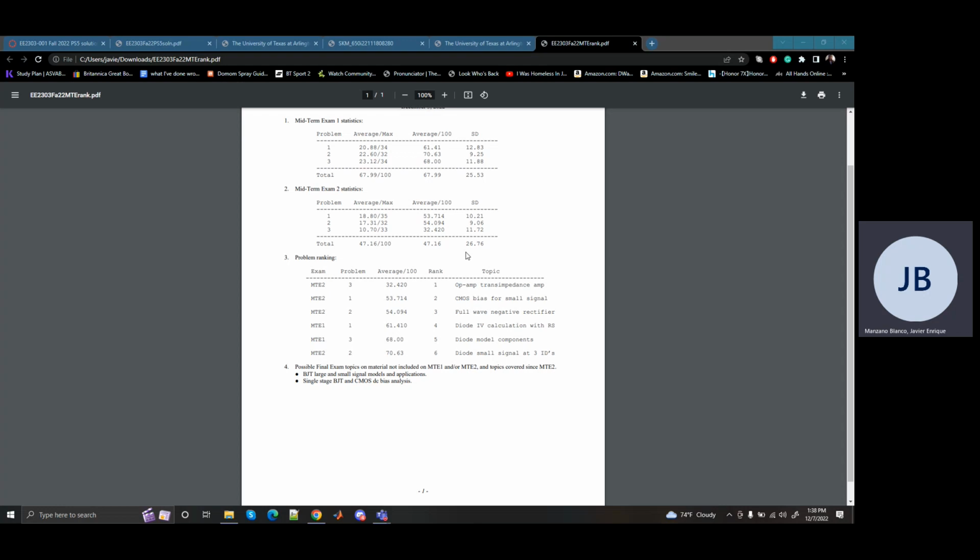Grace had a really good question yesterday: we look at input impedance, right? To this guy in the DC case, and that's these two resistors in parallel. In the AC case, it's different. In the AC case, we're including this. All of these capacitors become shorts in the AC case. So you're blocking DC so that you can set your bias level, and then your AC goes on top of that and it operates at your bias.